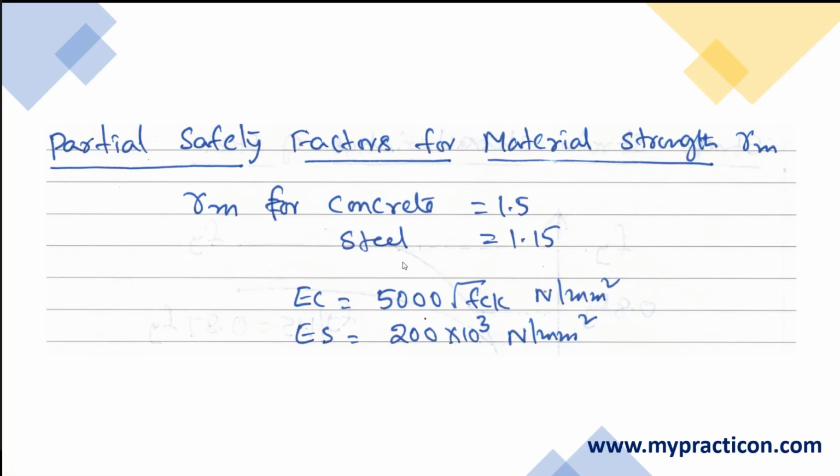In limit state design, partial factors are used to account for possible deviation of the strength due to manufacturing, accuracy of calculations, future risk to life, and economic aspects. The factors are 1.5 for concrete and 1.15 for steel.